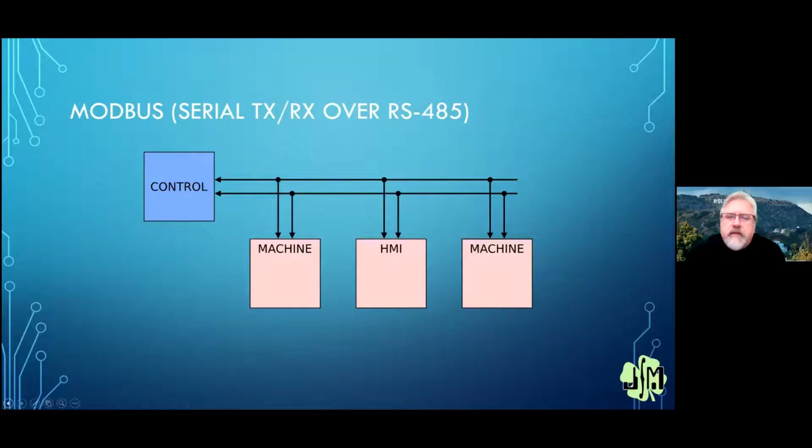It's easily implemented on the Propeller. I've done it on the Propeller 1. I'm rewriting a driver for the Propeller 2 because it's very popular in industrial environments. I know I shared in one of my other presentations a really big board that was the HVAC controller. We used MODBUS on that to talk to an HMI that was about 4,000 feet from the Propeller.